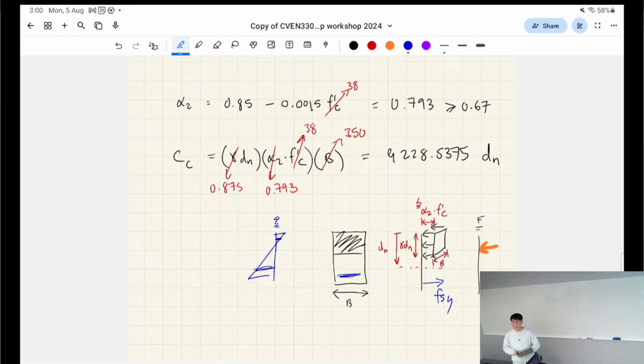Does that make sense? You always put more tensile bar in concrete than compressive bar for this reason. You add in more compressive bar, you're just wasting money. It's not going to do very much in terms of actually adding capacity to the concrete.